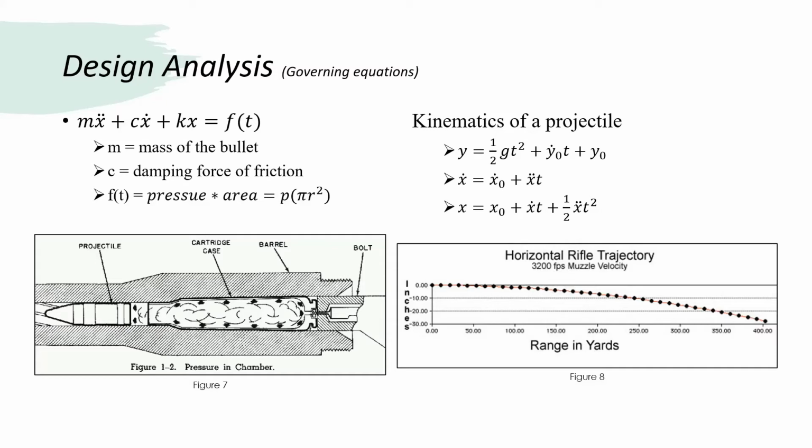Once the equations of motion of the bullet are determined, from these we can calculate the initial conditions for System 2. We know that once the bullet exits the weapon's barrel, it will behave as a projectile. By solving System 1's equation of motion, we have the initial velocity of System 2. With this velocity, we can calculate the bullet's flight time, derive its effective range relative to bullet drop, and predict its velocity upon impact. This is where our design process started, upon impact.